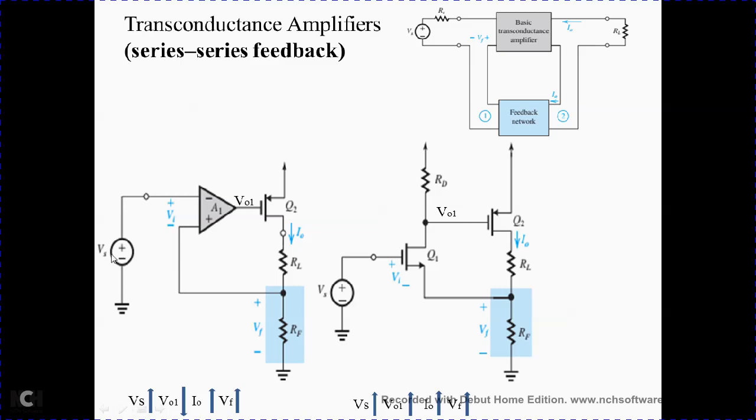So whenever Vs increases, V01 starts to decrease. Means if you are positive, it will give you negative. That is the meaning of it, right? Or else if you increase the voltage, this V01 will increase in the negative direction. V01 will decrease. Please remember, it is a P channel FET. So current I0 will increase. It will not decrease, it will increase because the input is decreasing here, meaning it is going more negative. For a P channel, a negative gate gives you more output current.